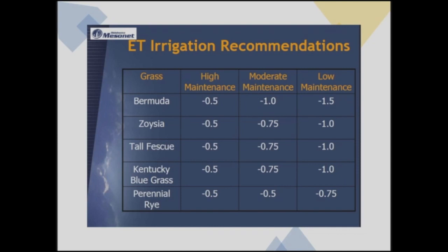If you've got the ET data and you kind of know how dry you want it before you make that next irrigation event, then this is where that would be useful. And so the nice thing about thinking about irrigation in this concept is you can set your run time from your audit to be that ½ inch. And so you know that every time you hit that threshold, let's put that ½ inch back. And so it kind of simplifies that system.